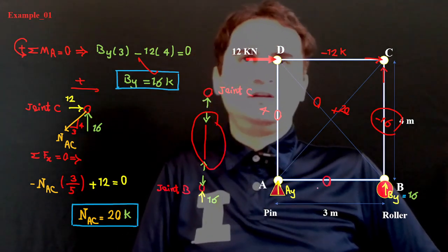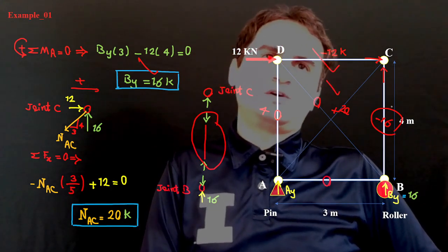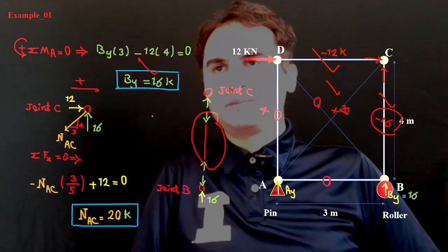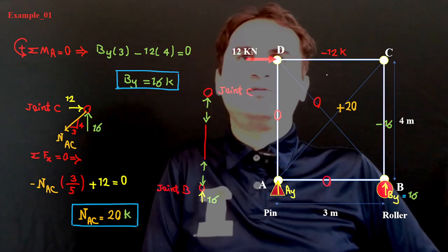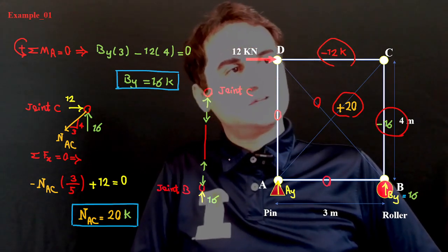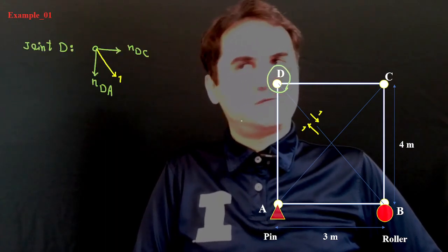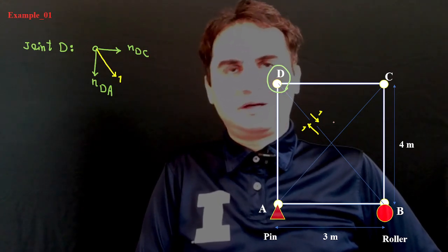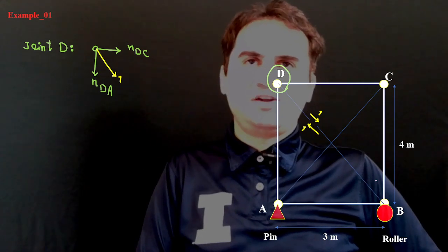Now we have the forces for all the members. So we have this one, this one, this one. The others are zero force members. As soon as we have that, we can replace the numeric value of each member of the structure and just move on. Now remove all the forces and then apply 1 Newton at each part of the dissected diagonal BD.